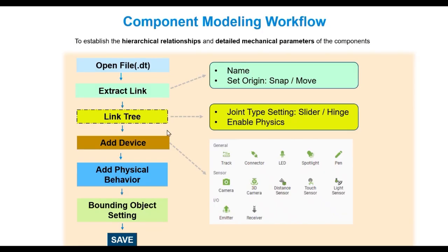In other cases, maybe we have a conveyor or gripper, and we will use add device. We saw some devices yesterday, but here it means we only enable CAD files that have the CAD features with some electronic component device behavior. We add the device in DIATwin, in the scene tree. And then we use behavior. Behavior helps you link the device and IOs and gives them a relationship, so you will know which IO controls which device.